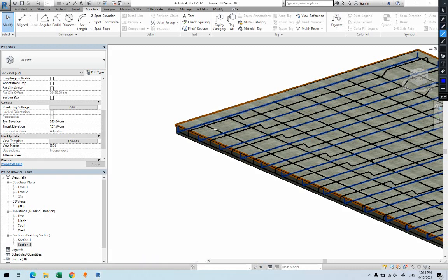Now additional, you have to draw them by yourself somewhere here. You'll add additional, however much is going to go at the top, you can provide them in between here. For example, there, in between the bent up bar. For the top layer, this is the easiest way to go from the sections. One of the sections you will go inside it and you will draw this line from the top. The length of it you will know from the design. Remember all of this length, all of them will be shown on the design, because when you're using design it will be shown.